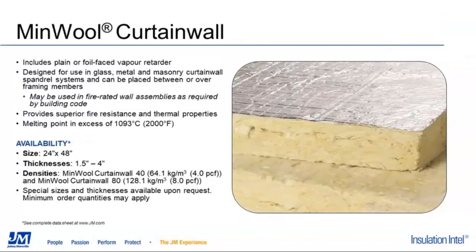This can be faced with a foil facer, as you see in the image there, or it can just be unfaced as well. This goes in your curtain wall spandrel system. So this is typically a little bit more custom. This is where architects can sometimes get creative, creating some odd size exterior panels.